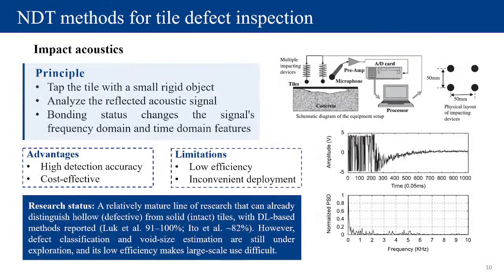And here come the corresponding non-destructive testing methods. The first one is impact acoustic. In real cases, labor would tap the tile with a small rigid object and analyze the reflected acoustic signal. And impact acoustic could be used to detect debonding tiles.